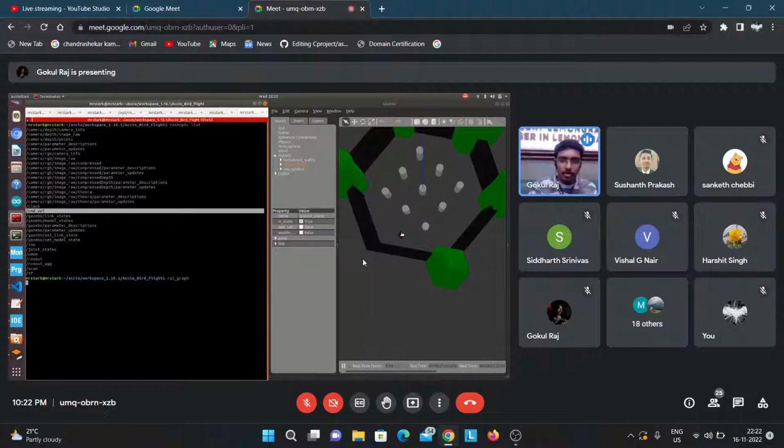Now, when I move the joystick, you can see the robot moves. Now imagine this robot has an individual system, like 2 motors with the Arduino, where you wrote code to publish PWM based on the data it receives from a subscriber to cmd_vel. And this is running on an ESP32 NodeMCU, so it's running on Wi-Fi.